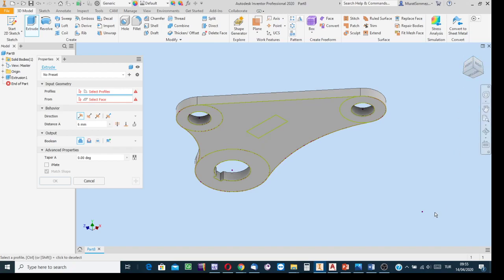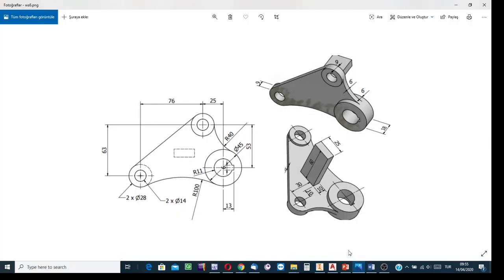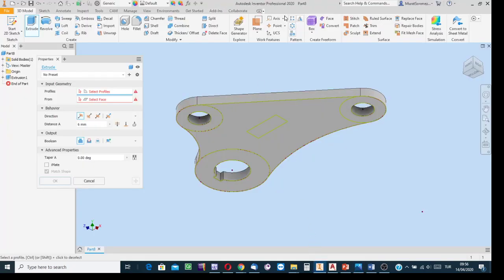At the frontal side, look carefully one more time. At the back side, there is a rectangular prismatic extension. Its length is 60. Let me create this prism first. Indicate this profile, this part. It is a region bounded by the rectangle as the profile, and then extrude.